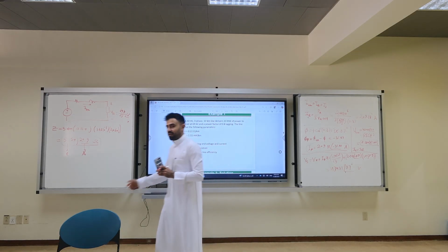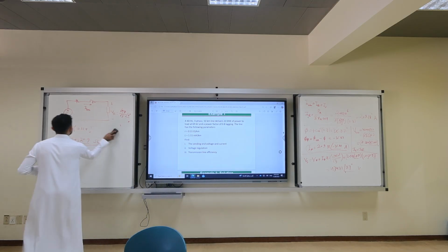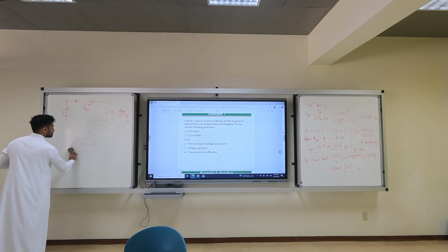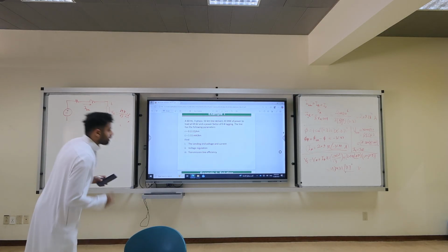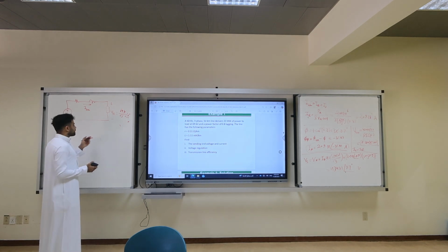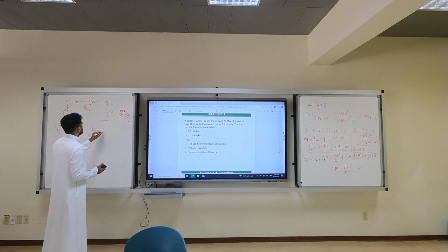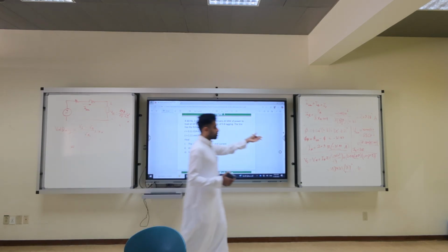Now let's calculate the voltage regulation. What is the equation? No load minus full load over full load. I'm not going to call it VR, so as not to confuse it with the VR. It's VS minus VR over VR times 100. You can use the line to line quantities, or the phase.